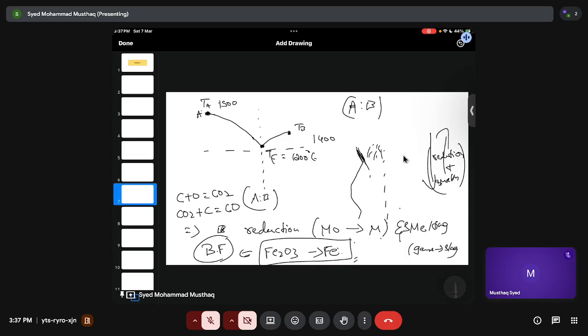When reducing with carbon, it always requires high temperatures, because whenever you oxidize carbon it will form carbon dioxide, and to maintain the conversion of carbon dioxide to carbon monoxide you need to maintain high temperatures. So that is one drawback. But the next good thing is it can bear your load. And sometimes some metals may form carbides when they react with carbon. Again, that is not good.